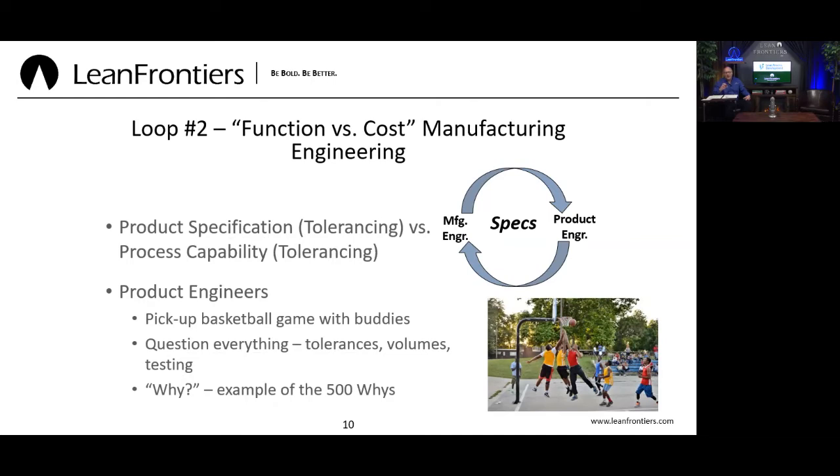So for example, there was a call out on a part I was working on, a geometric tolerance. And it was very tight. So I questioned them on that. And they kind of said, well, that's what's always been on our drawings for that particular component. And I had spent time going out to the shop to ask the foreman of the department, because he'd been there for 30 plus years, is this something that they hold? And basically what I found out from him is they had never held that from a capability standpoint as long as he had been there. They'll come out and do capability studies to find out they're not capable, but ultimately they need to get product out, so you keep going there.